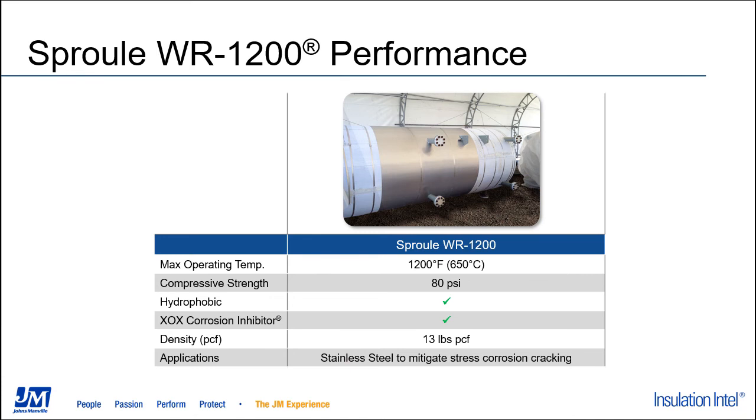Also rated to a maximum of 1200 degrees Fahrenheit. The compressive strength rating is 80 psi, so not quite as good as the calcium silicate, but still very good for areas at risk of mechanical impact and damage.